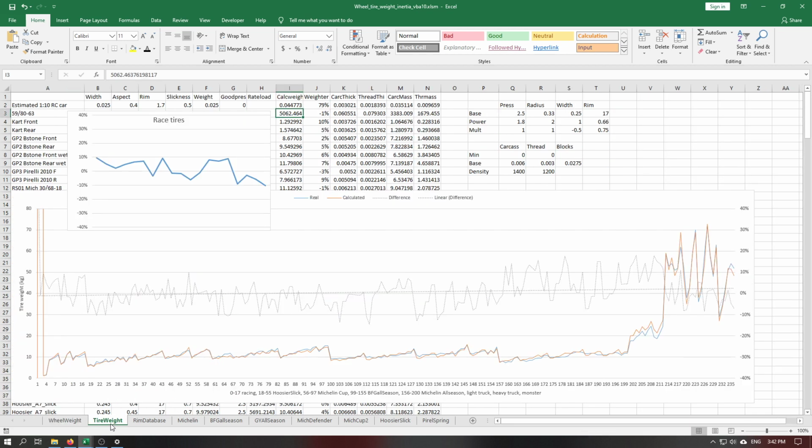So, this is probably my way of making sure my channel never grows, but I'm sure there's one or two of you out there who found this interesting. And in the meantime, I've been doing this really occasionally because there's not a lot of time. I've done the same for load sensitivity for tires and also aero maps. I can now make aero maps that make sense and that have adjustable sensitivity for pitch and ride height, with just a few parameters, and I get aero maps that match like the LARA data.